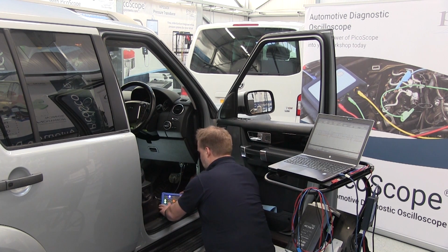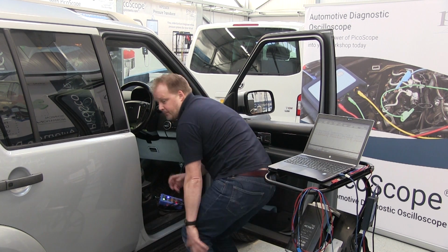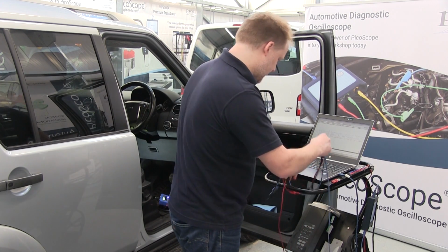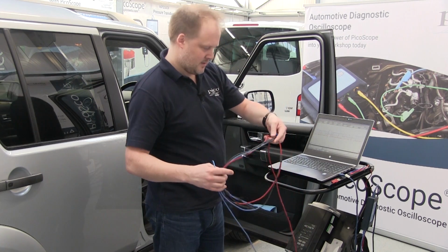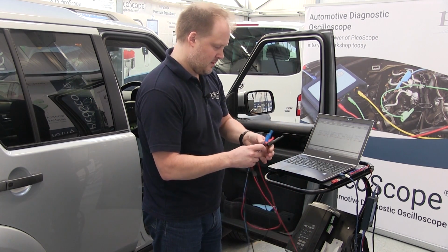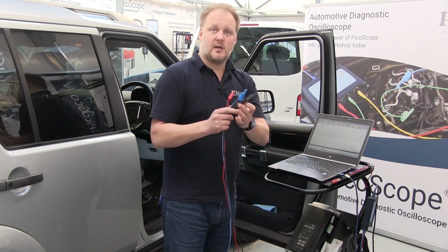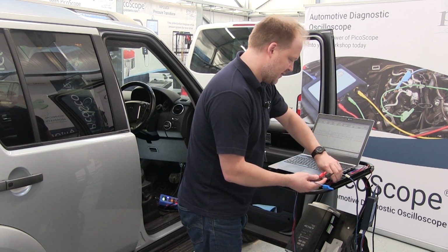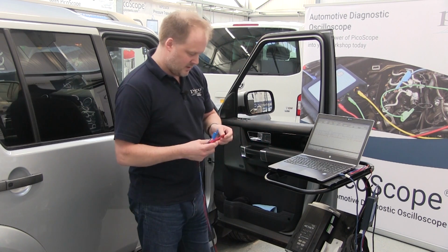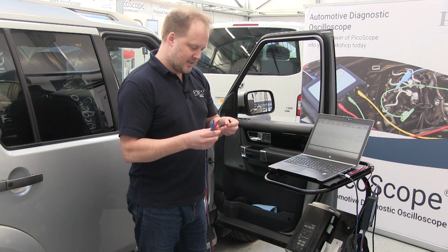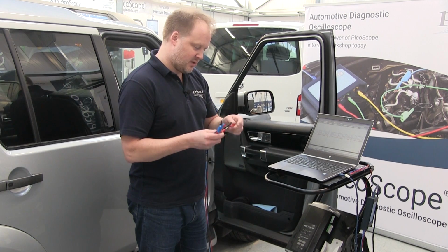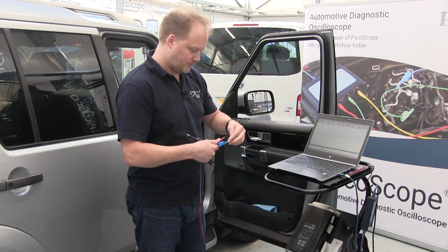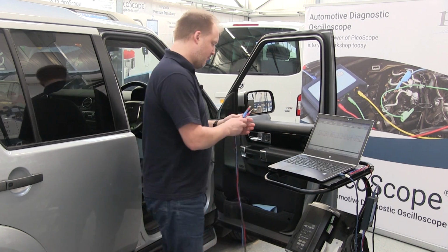Let's connect our scope into our breakout box. We take our test leads. Again, we've got our earth fly leads joined together, and we need to use some adapters actually here to get our x1 test leads into the breakout box, and we'll add those.